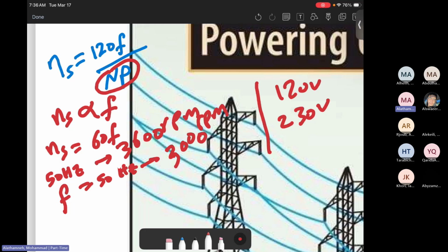The other thing, again, 120 is safer, but sometimes it's not sufficient to supply large power elements like the air condition units or water heater. They can absorb a lot of power, which makes 120 volts insufficient. Therefore, the central air condition in United States homes is connected to 240 volts.